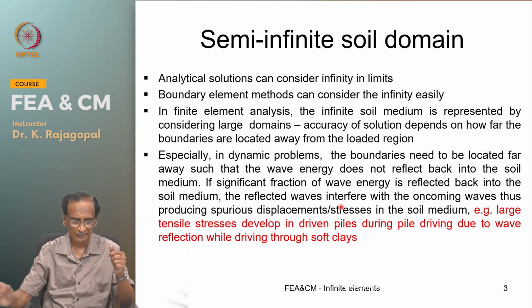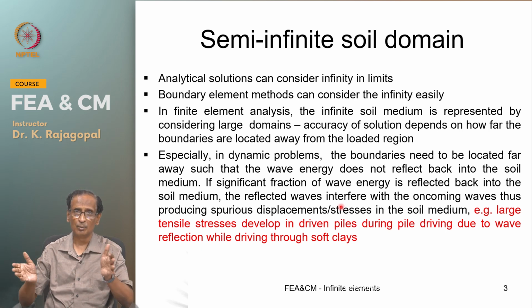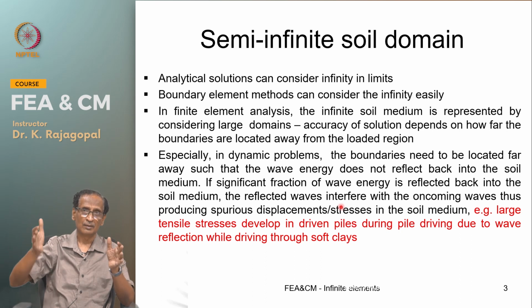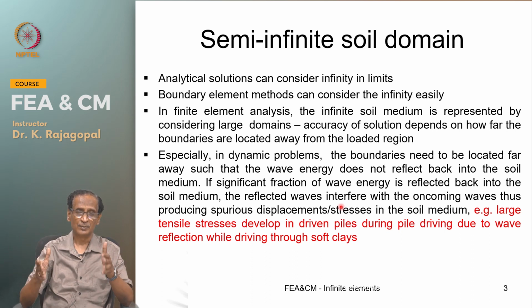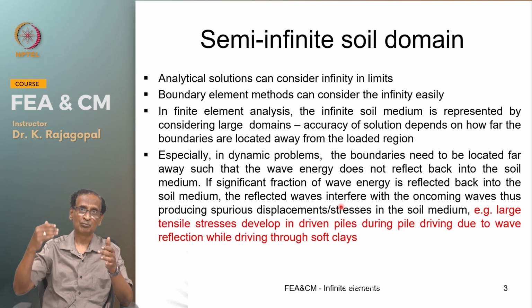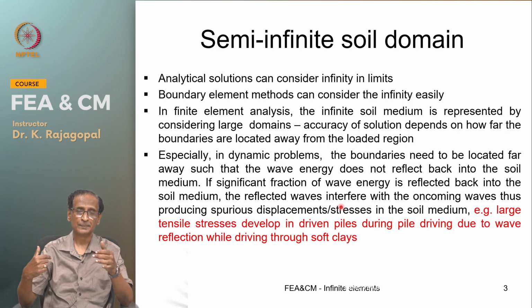One simple example that I can give you about the reflected wave is, when you have a driven pile, you know that you are giving energy at the top, and if the soil is strong enough, it will absorb the energy. If the energy that you are imparting to the pile is much higher than the resistance, then the pile will be driven into the soil. And when you are driving and you give a large energy and suddenly let us say you come into a soft clay, obviously it will not be able to absorb the energy that is coming from the pile.